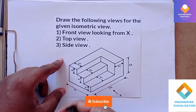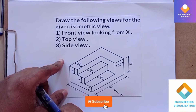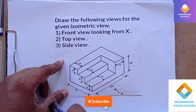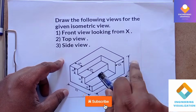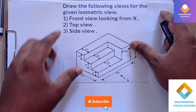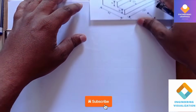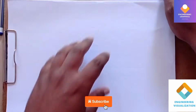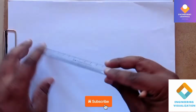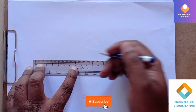So we have to analyze each of these views and we need to construct the front view, top view and side view. They have mentioned in the question that front view looking from X is your front view. Then you can see there is a top view, and there is a side view. So we will be constructing each of these views one by one. First I'll be constructing the XY and X1Y1 lines, thereby dividing the regions for the top view, front view and side view.